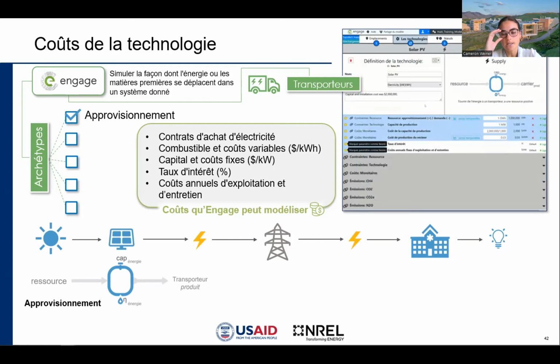So with that in mind, let's go back to the solar technology and think about the costs that we've configured. It would be wrong for us to keep both costs listed here, since a power purchase agreement kilowatt hour cost usually bundles the fixed costs of the renewable system with the variable costs.